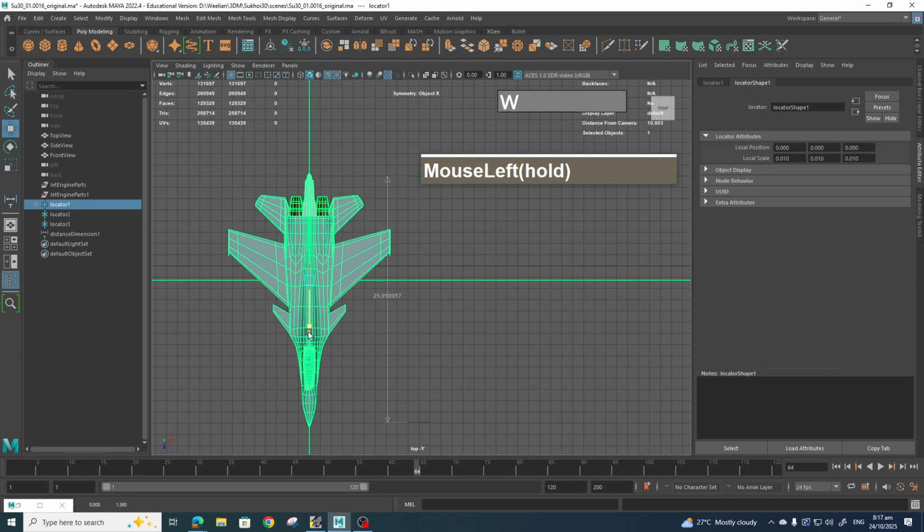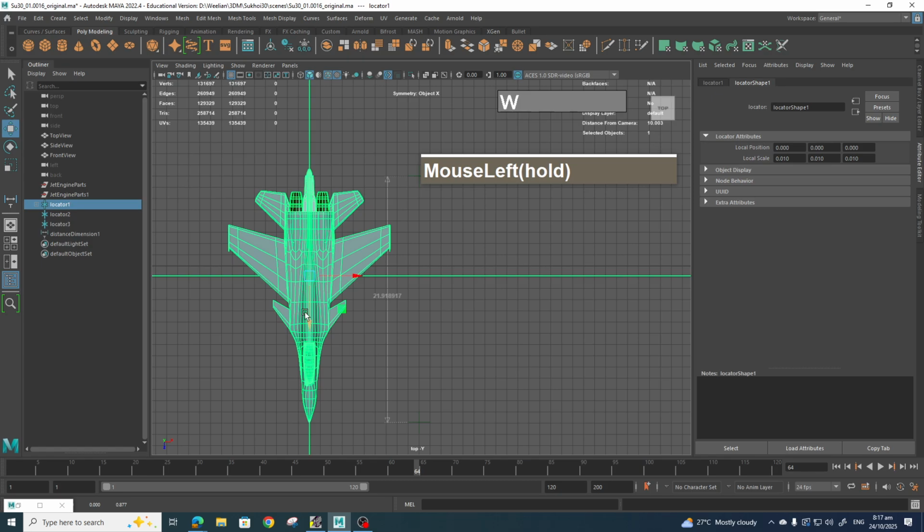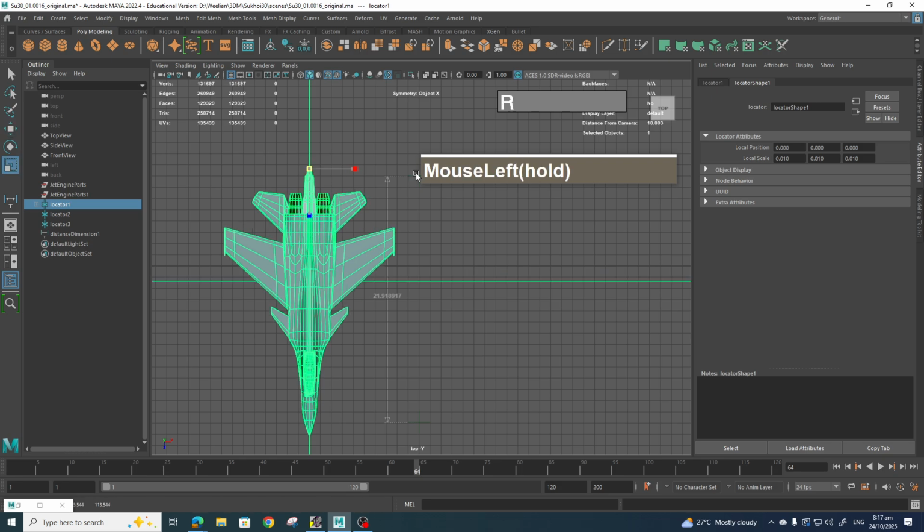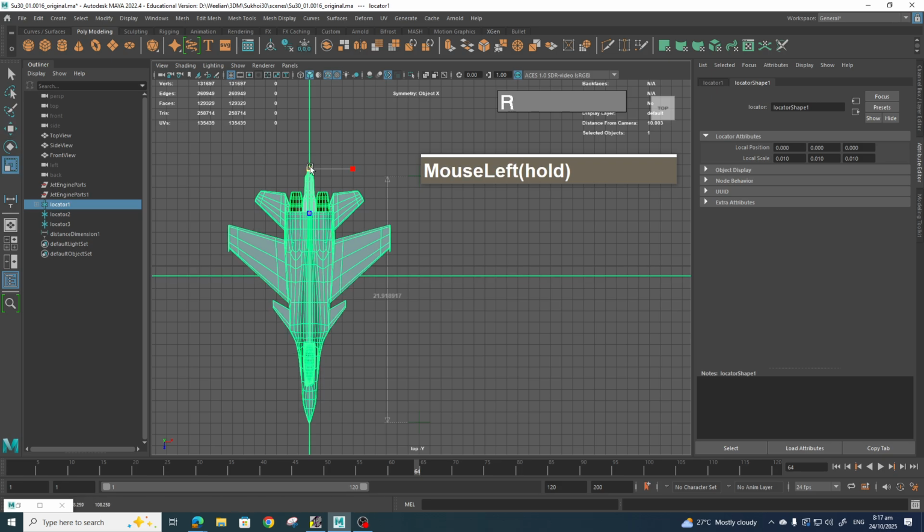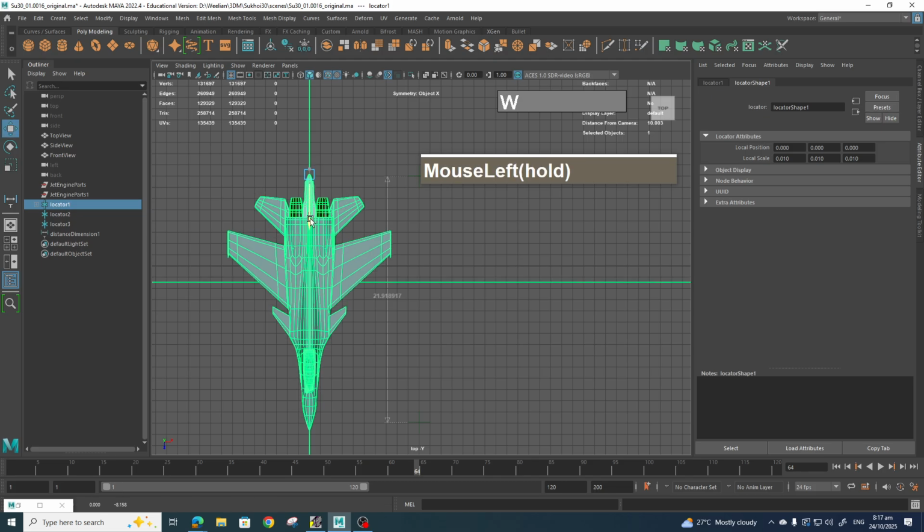it matches. Now, if you want to scale it, I'm not sure whether I can change the pivot point of this. Well, actually I can. So you can move the pivot point to the tail here. Then press D to get out, and then you can use scale and uniform scale so that you can grow it from one point. Okay, so that is one way you can scale the aircraft until it matches the dimensions.